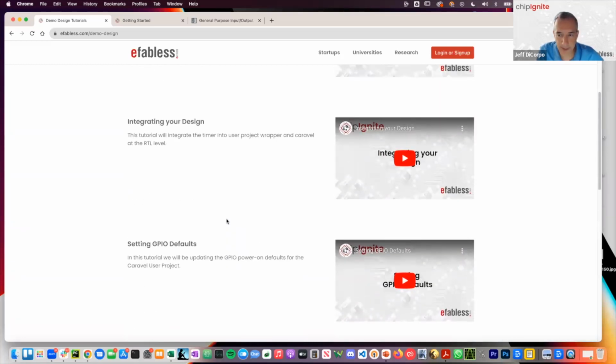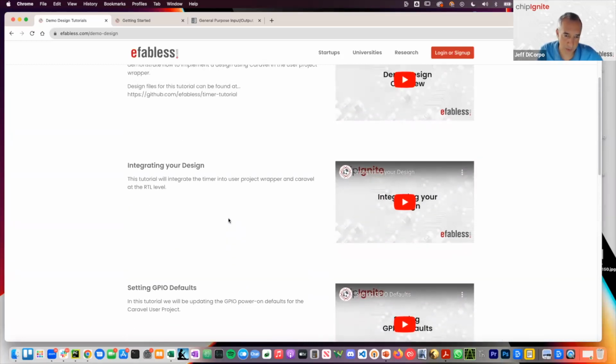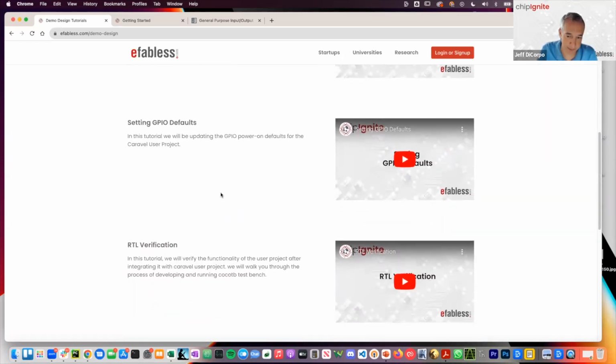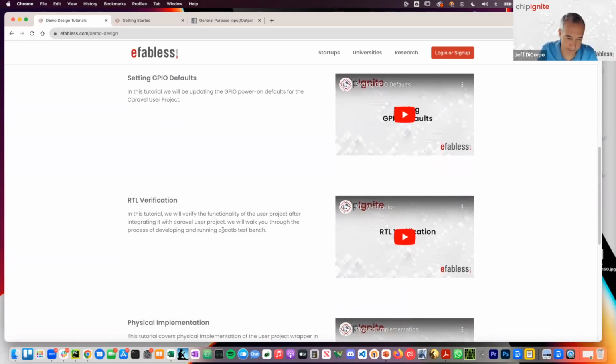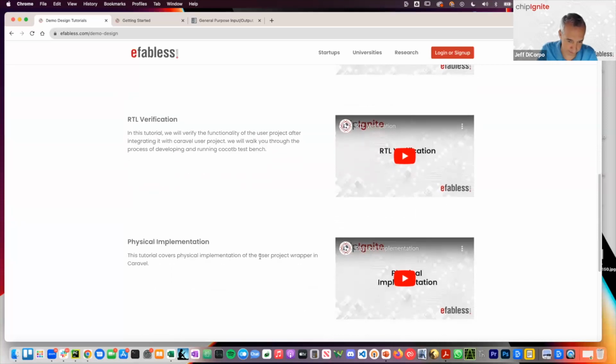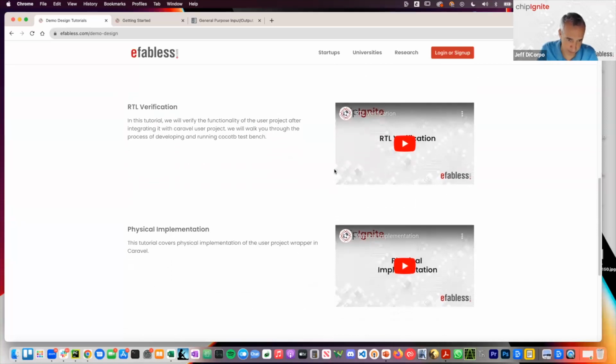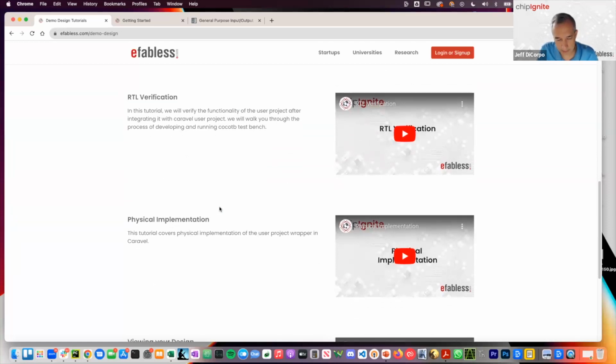Hopefully, by the end of this webinar, you're going to have a pretty good sense of what the overall process looks like, how to implement a digital design once you already have your RTL, how to integrate that into Caravel and run OpenLane to implement it physically, as well as run RTL verification for it if you're doing that, using our tools or flow, and then also how to submit that on the Efabless platform.